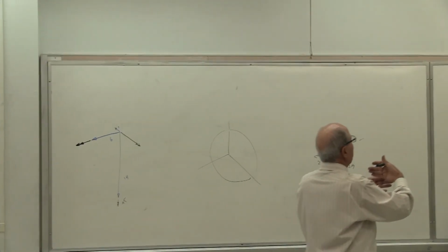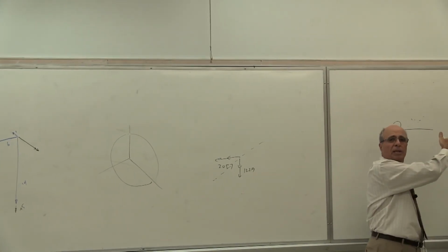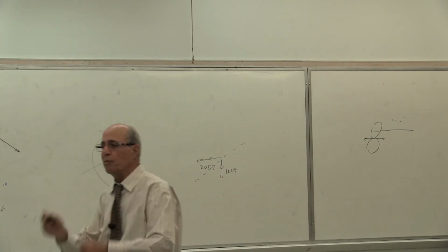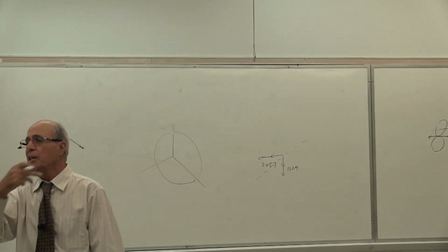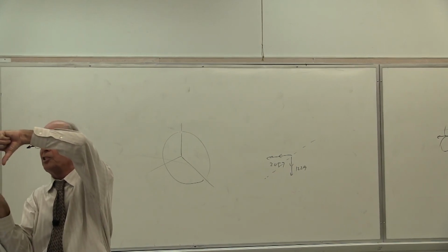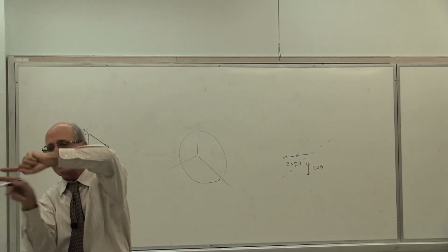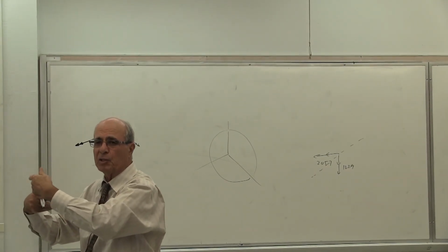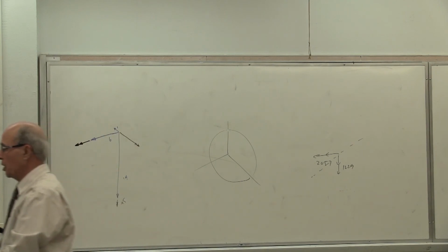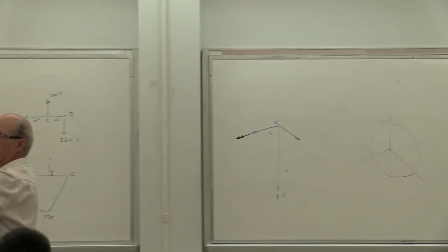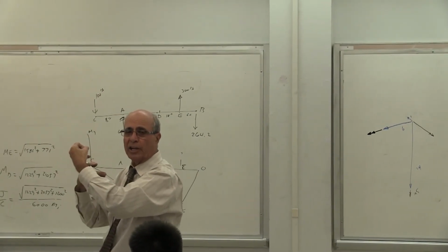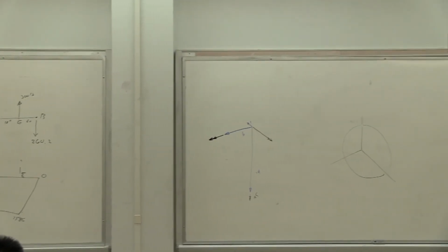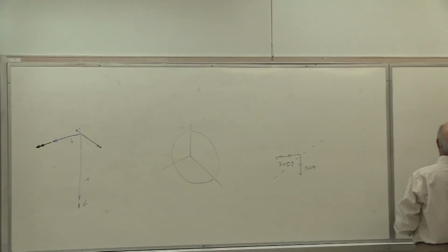The forces could be in this direction, or the forces could be in that direction, because the gears on top of each other create forces that depend on which way they move. If the two gears are like that on top of each other, the forces here are equal, and if they are this way, moving along here, the forces are like that. So it could be vertical or horizontal, remember one more time. Two gears on top of each other create the forces in the Y direction. You learned that in statics, that you separate these forces depending on the type of motion, which way you go.